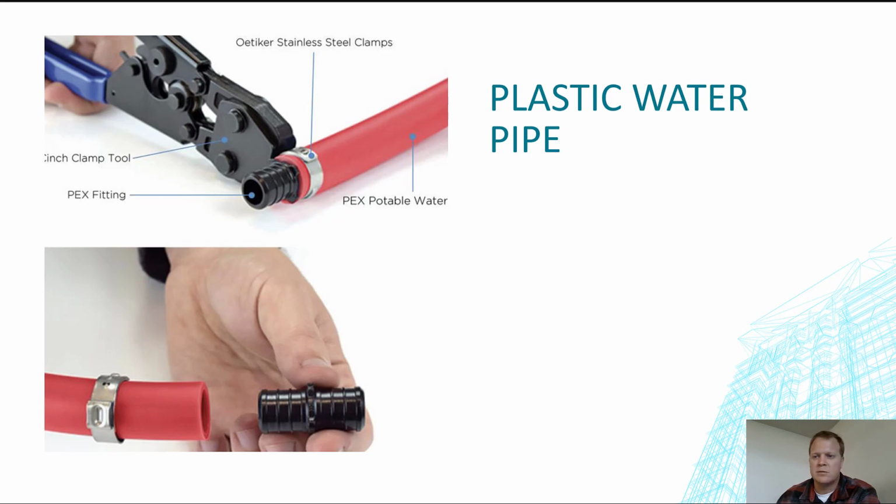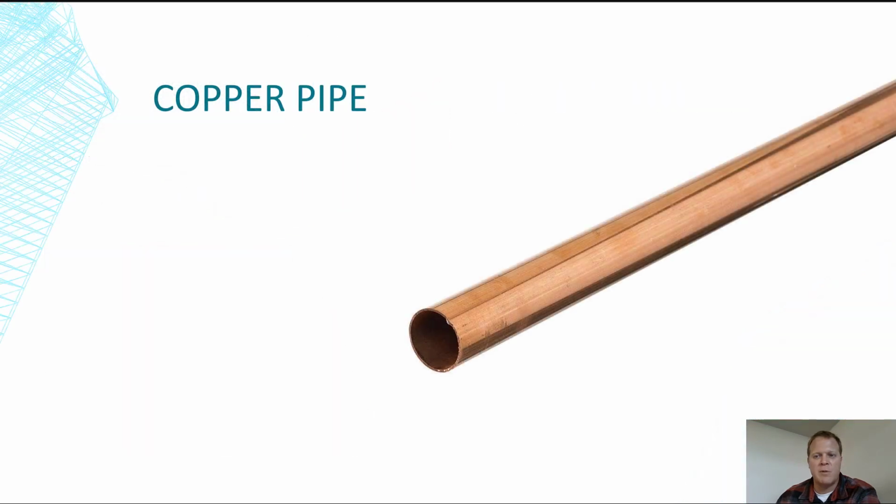it's like 3/4. And so moving on, we've got copper as a water conveying material, and copper has different wall thicknesses and stiffnesses, and you have K and L and M and all different types of copper piping. I'm not interested in sharing all the details about the different types of copper piping. Just know that copper pipe is one option for conveying water, and I think it's type L that goes underground. I think joined by soldering is usually, or you could braze, or you could do a compression fit, or you could do a mechanical fit.